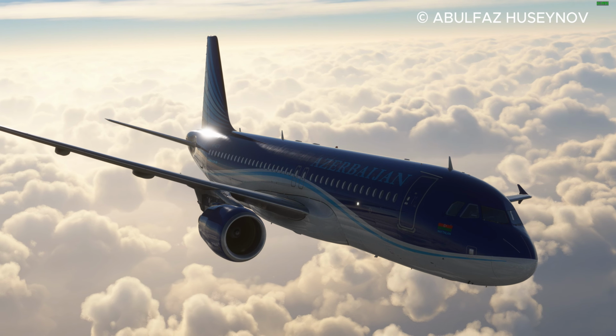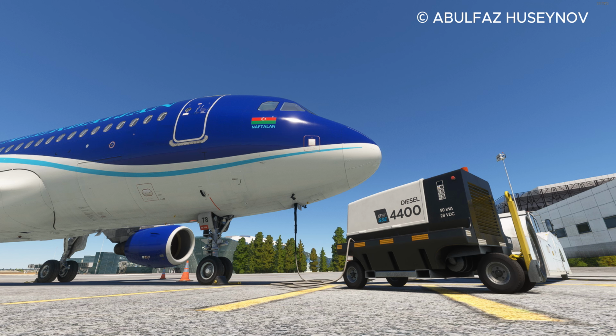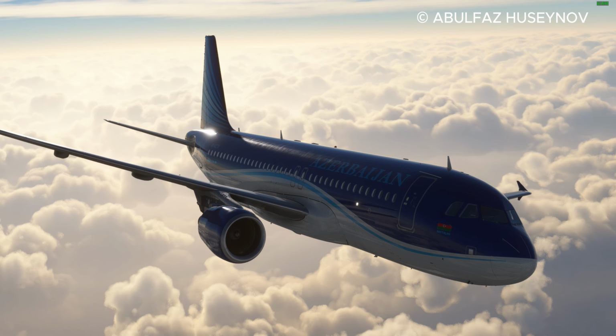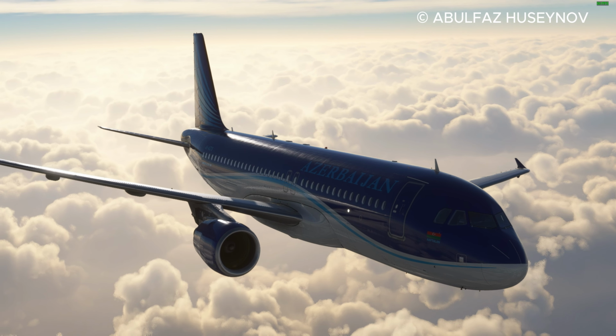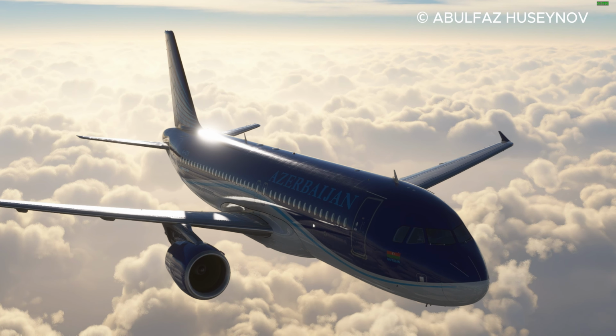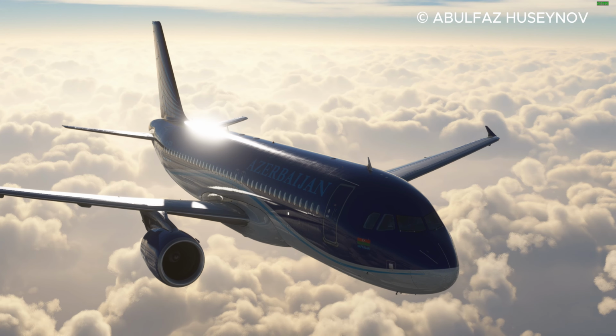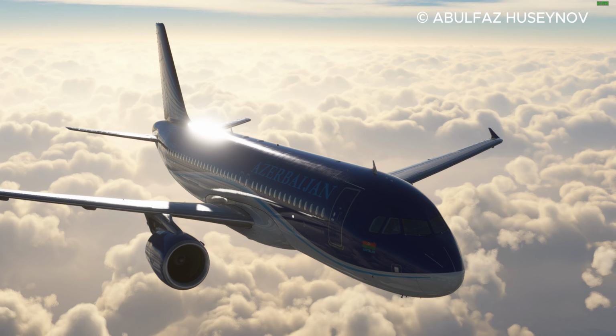The A320 has 5 primary electrical sources: batteries, ground power unit (GPU), auxiliary power unit (APU), integrated drive generator (IDG), and the Ram Air Turbine (RAT). We'll also delve into the differences between DC and AC power and explain the role of the static converter in this sophisticated system.